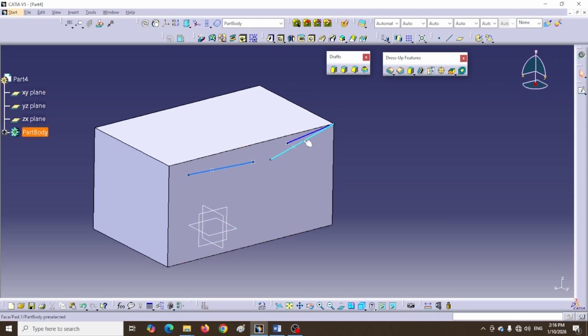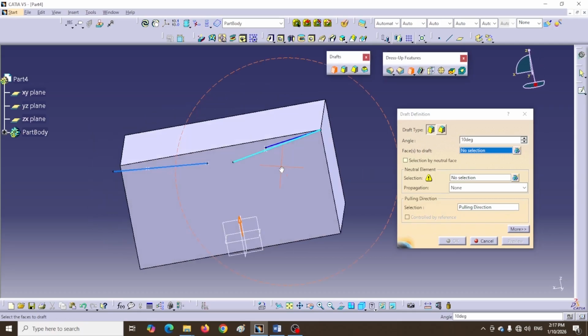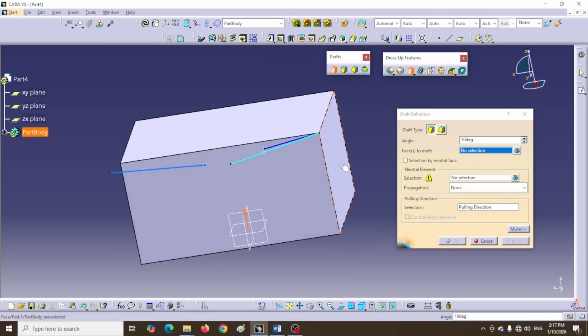Now, what effect does selecting, for example, a diagonal line have on the design part? If I select a diagonal line, a 10-degree slant is applied relative to that selected line. In this case, the initial shape of the cube changes according to your selection. Now, there are important tips here.